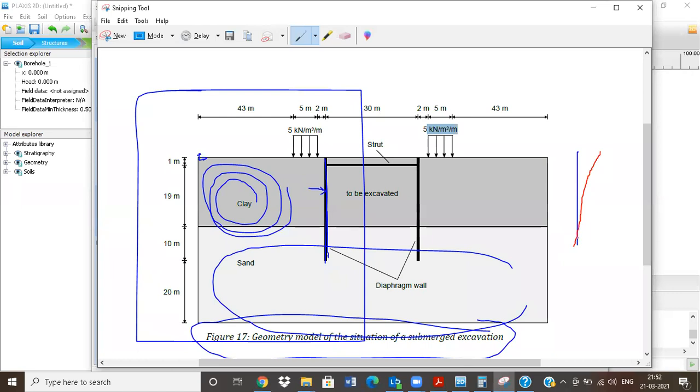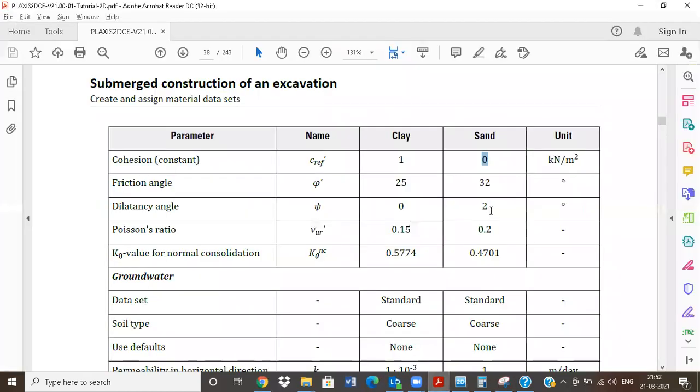Okay, so whenever the position changes, it comes over here, which is like this. This particular thing we want to capture at the tips, which are not fixed. These tips are coming inside the soil layer, inside the sand layer. That's why they feed this value as 2, to identify the shear forces as well, which may go beyond the yield. To identify that, they have identified these interactions, so they have fed this as a 2 value.